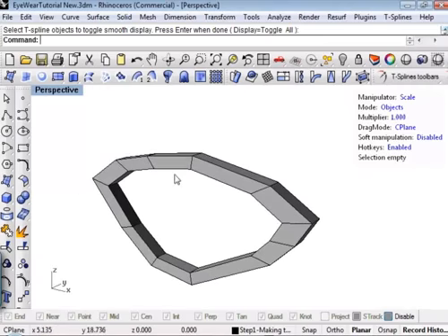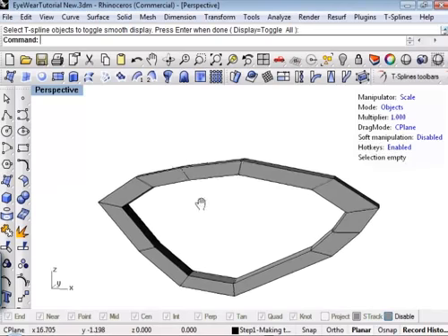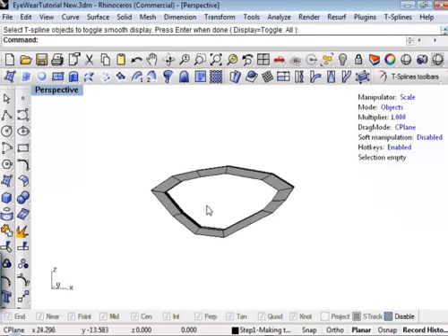Box mode may be an easier form to work in when you're getting started because everything's fairly clear and fairly well laid out. If you're having problems with your model and you look in your box mode and something's really screwed up, like there's verts that are crossed up or a face that's turned inside out, you can be fairly assured that that's going to be the problem. If you address that issue in box mode, when you go back to smooth mode, that problem will most likely resolve itself.